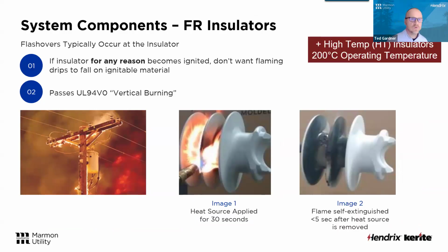We also make a flame retardant version of our tie top insulator that will melt, but it won't ignite. It's a proprietary material that we use, and we also have a high temp insulator. We've got a handful of customers that like to run their systems a little bit hotter than normal, so we've got another blend that has a higher melting temperature. It's not considered flame retardant, it's considered high temp. So we've got two different versions of that. Those will let you run about a 200 degrees C operating temperature on your conductor before any damage occurs.